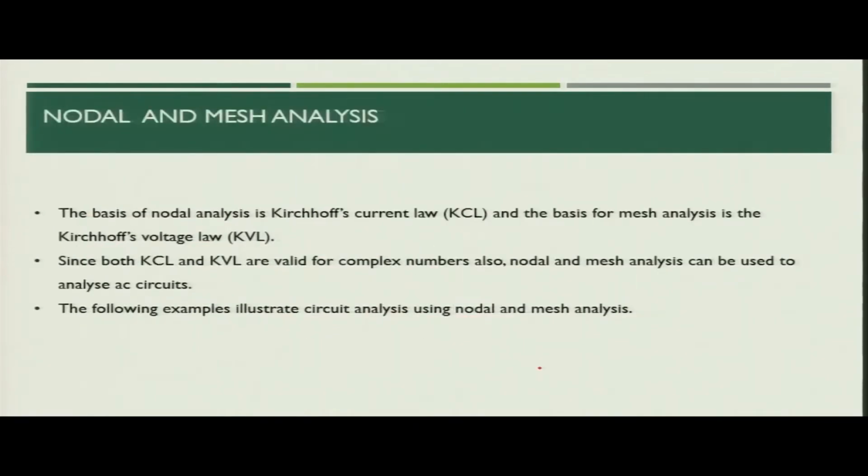So, let us try to understand the nodal and mesh analysis first in case of AC circuit. So, the basis of nodal analysis is Kirchhoff current law, and the basis for mesh analysis, that is also called as loop analysis, is based on Kirchhoff voltage law.